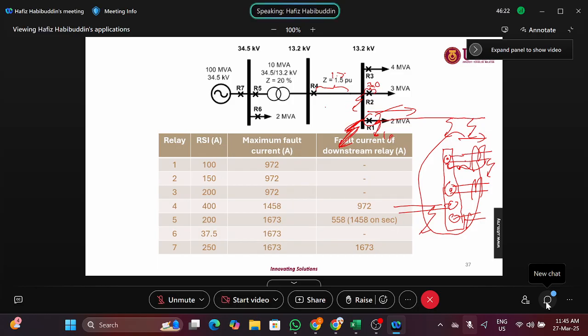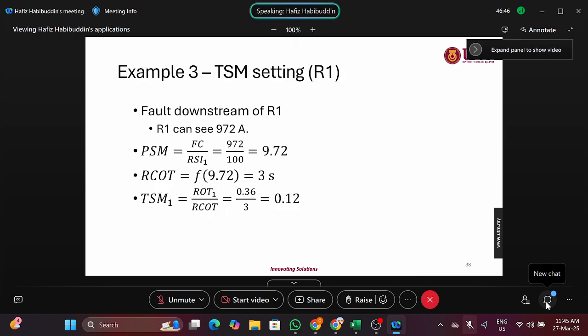We do fault analysis on the bus anyway because we have parameters, the transfer impedance, I mean, the impedance between buses. We have Z between bus A and B. So that's why we do fault analysis on this. So effectively the same. So you have all the fault current there.